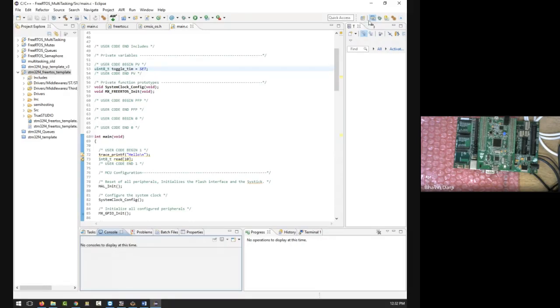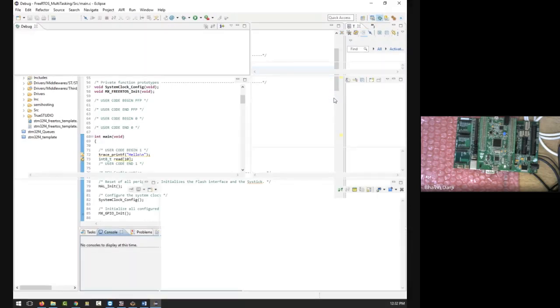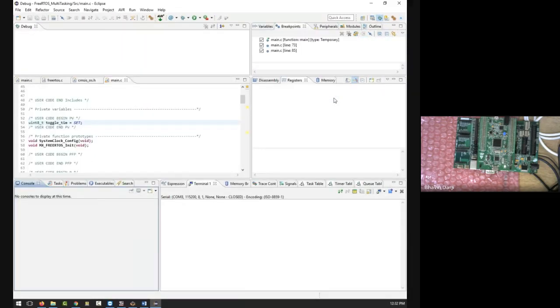And there is also a debug window. Debug is a whole new interface. When we debug our microcontroller kit or our program, it will start this different window, and here we can execute our program step by step. Each and every step can be executed one by one. These keys are currently disabled because we are not debugging any program. You can step into, step over, and step return. Using this kind of key, we can execute our program step by step. And below that, you will see the location of our current program.